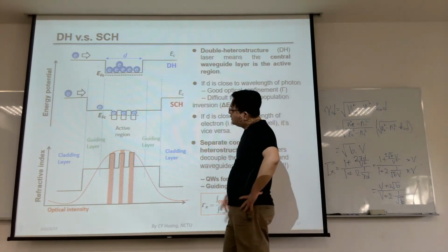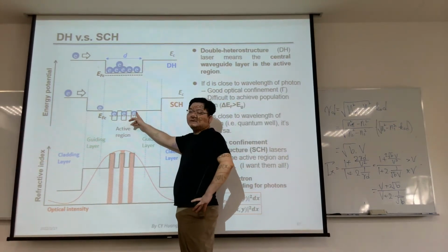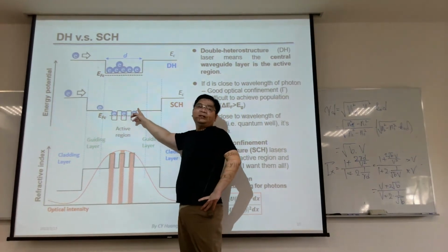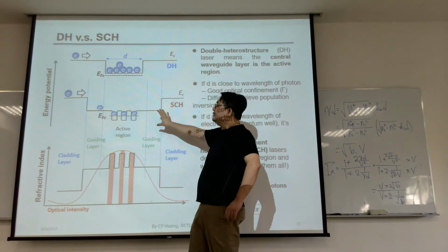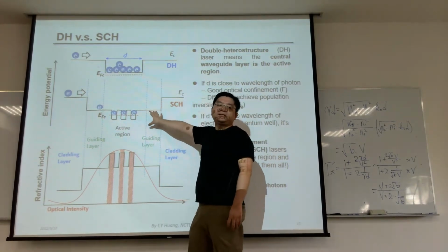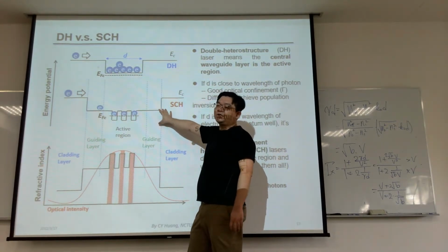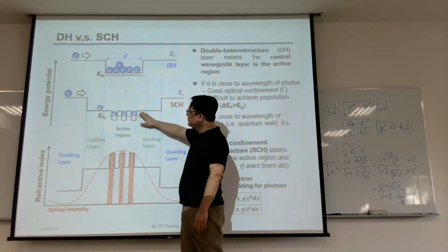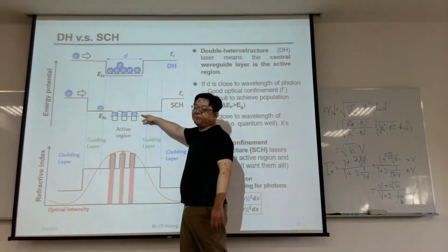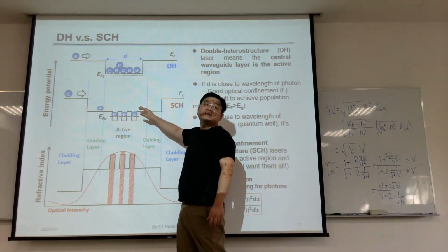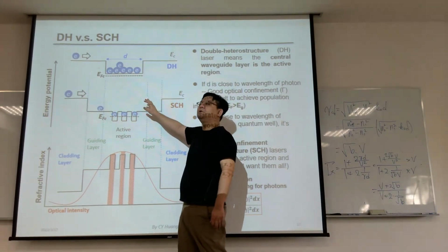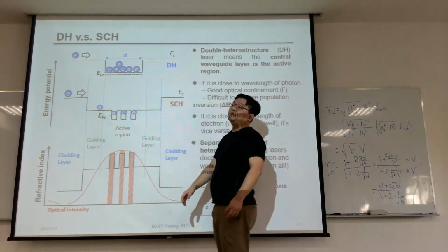But the high concentration might compensate for the sacrifice of confinement. Since you need much less carrier injection to let the Fermi level surpass the ground state in order to get the population inversion.